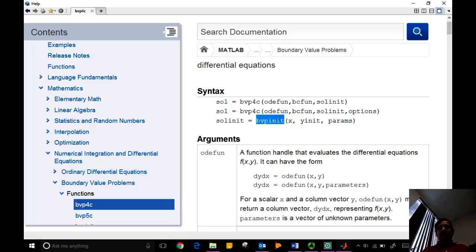Maybe I should have started it with COMSOL, because you will see the process in COMSOL visually. Okay? But in MATLAB, you need to define what that initial grid distribution is through that vector. And similarly, you need to specify the initial values for your state variables. Now we have formulated as two variables and two unknowns, y1 and y2. So I need to specify what is y1 as a function of x in the entire length, and what is y2, which is theta prime, as a function of x over the entire domain, 0 to 1.